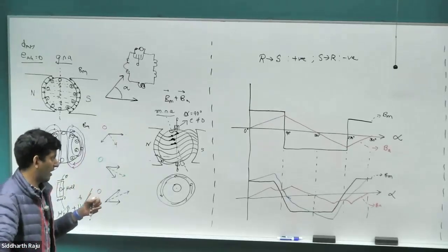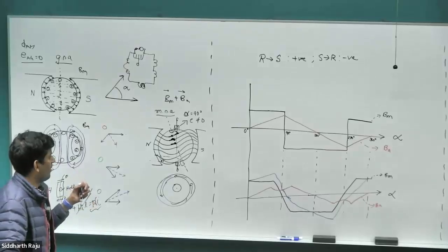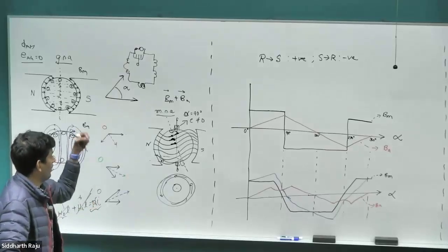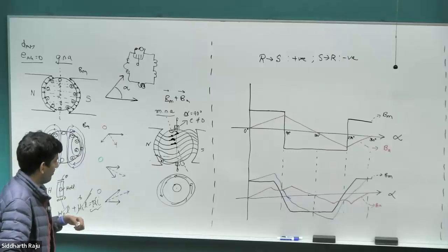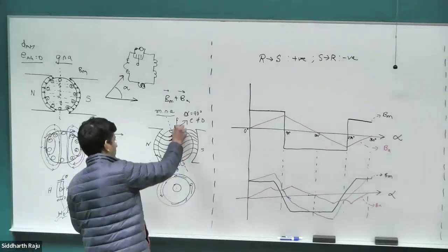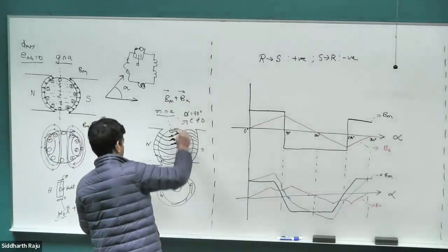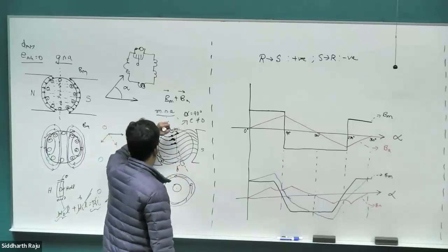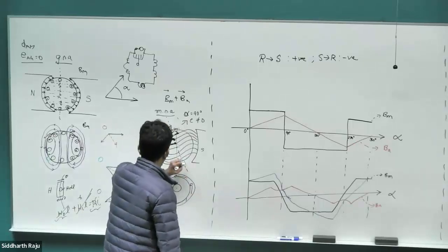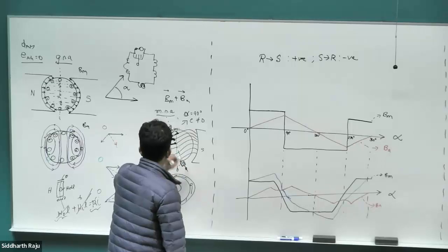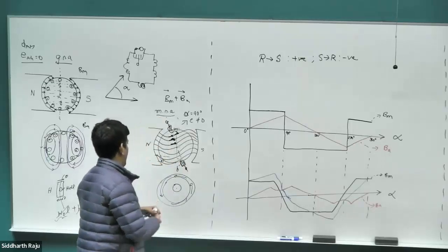I posted a video on Canvas for that. You can take a look at the video where it will clearly show the DC motor starts to arc. So the obvious solution for this is to shift the brush. So this was one of the solutions that we saw, where we can just simply shift the brush and we can call it a day.